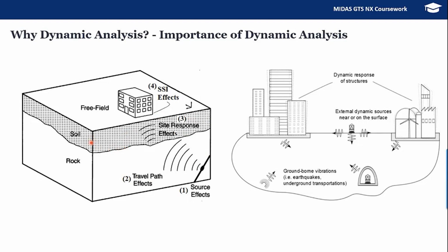Now let's see, if there is a sand layer over here and it's completely saturated, then because of the earthquake load, there is a high probability of the pore pressure increasing drastically, and that may result in liquefaction. In many cases of building foundation design, we generally neglect the liquefiable layer and proceed with analysis. But as you know, as the soil behavior changes, the effect of the load applied on your building changes drastically.